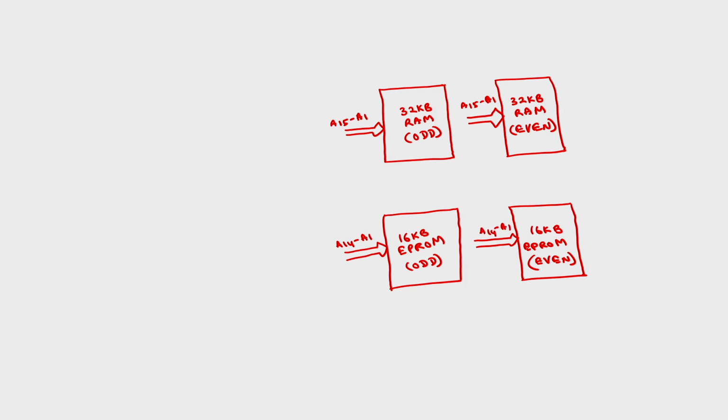So all the 4 buses you are going to connect to the common bus of 8086. Now the question is, how will these 4 devices be differentiated? At any time only one of these memories will be selected, so the data transfer will take place with that particular memory. Even though this common bus of 8086 is connected to all the 4 memories, at any time only one memory is selected, so that the data transfer takes place with the selected memory.